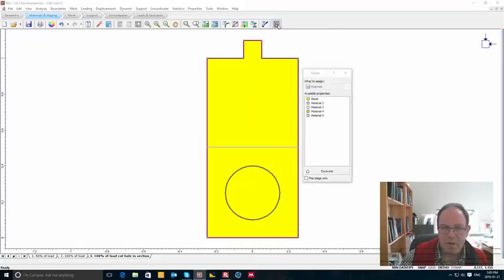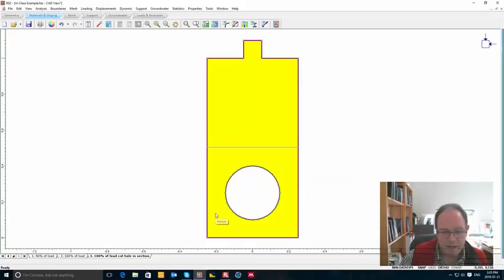So you can assign the material properties tab. This is when you can assign different materials if you have multiple materials. But we're going to excavate or cut this hole. Okay? And watch, I'll cycle through the stages, and you can see it's only cut in stage 3. Okay. So the material is solid in stage 1 and 2, and then in stage 3 the cut has occurred. Good time to save. All right.